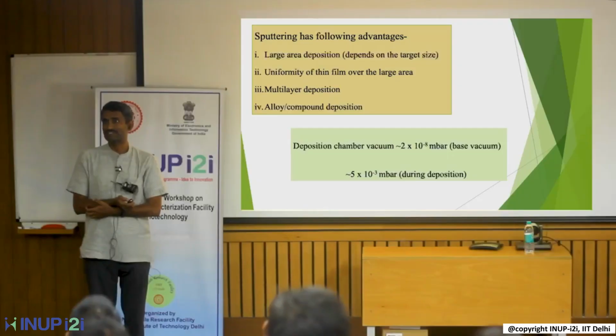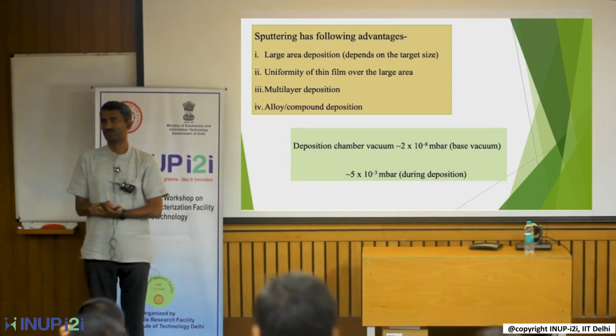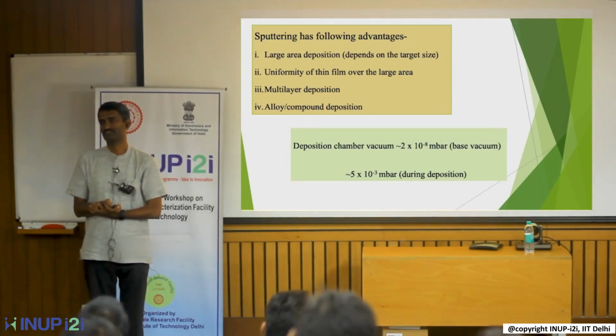So this is during the deposition, right? You evacuate the complete chamber. That is important, the base vacuum. Basically, that's what we want, right? Sometimes moisture, even the water content, even the oxygen, are all going to influence the film properties. So that's why reproducibility matters.